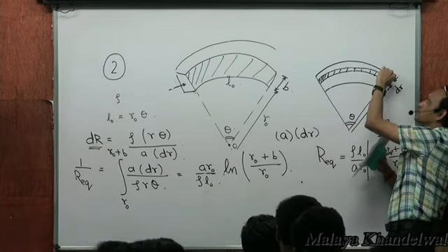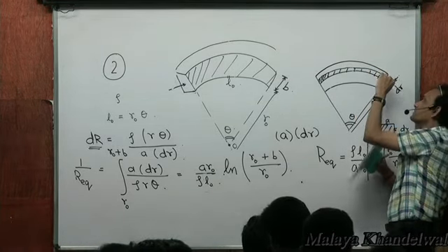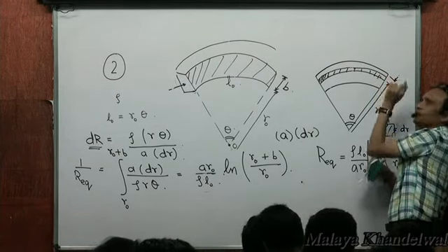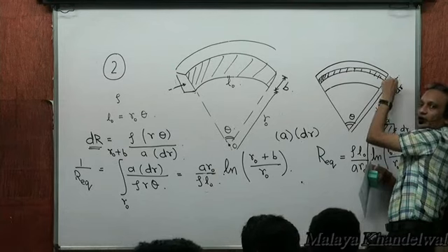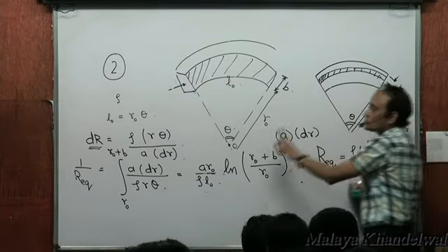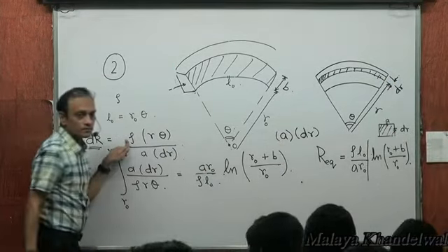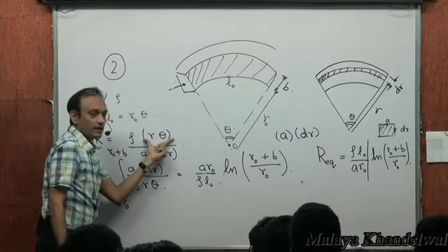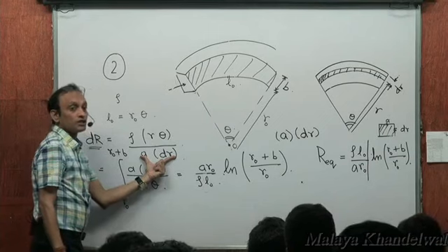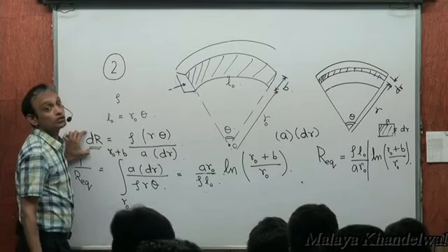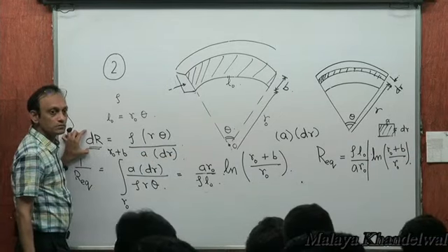Its thickness is dr, and what goes into the plane of the board is A units. So this is a rectangle A into dr, right? So specific resistance into the length L, rho L by A, area of cross section. That's the resistance of this chosen shaded conductor.